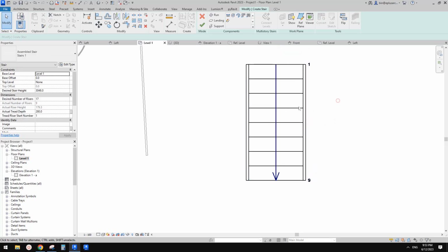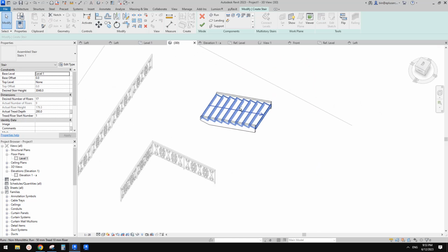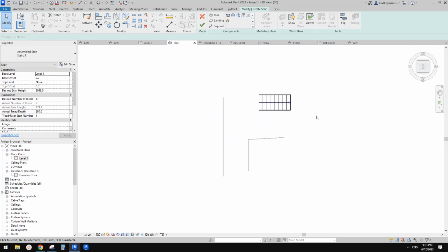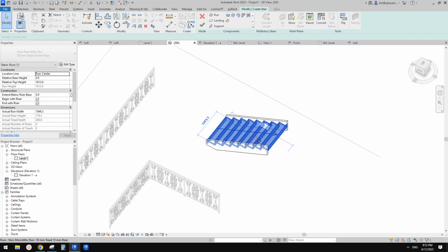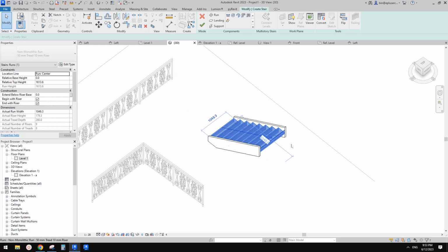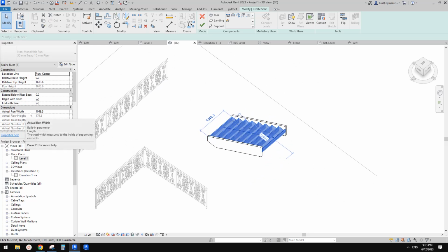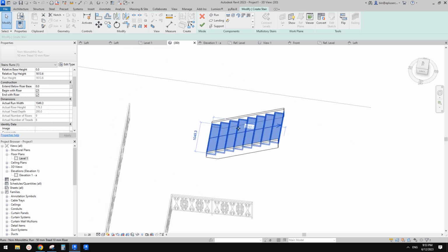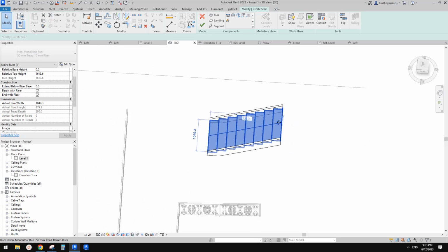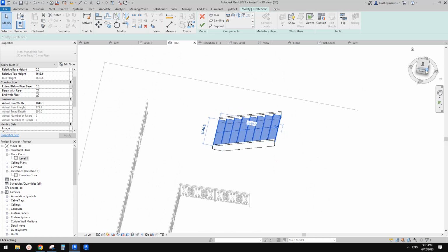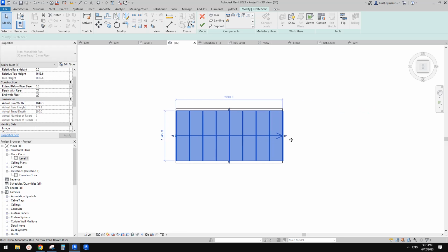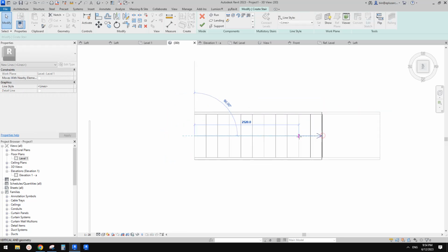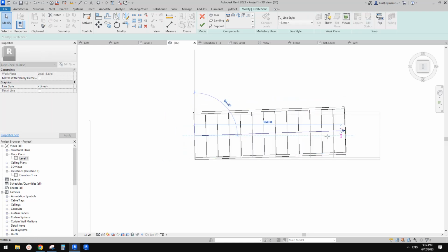It's very simple, right? Another option is in 3D view, you can also click on the top, and then you select it again. So this time, you can see in this view, if you select the stairs, you won't be able to adjust. You can adjust the width by typing a number here, but you can't increase the number of treads here. So you need to just click on the top and then unselect it and select it again. So now you can do the thing. Usually you can only do it in floor plan, right?